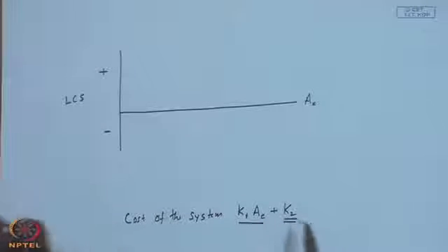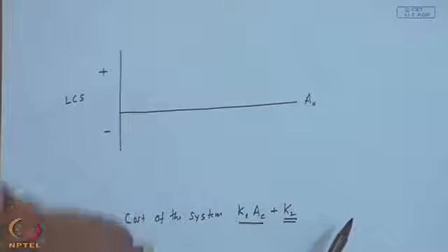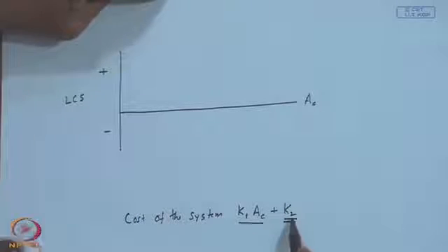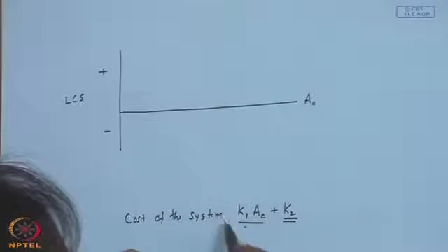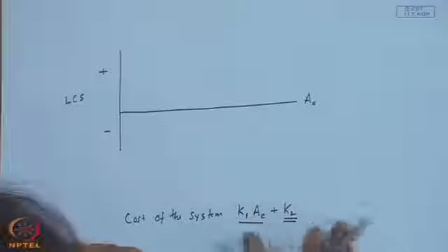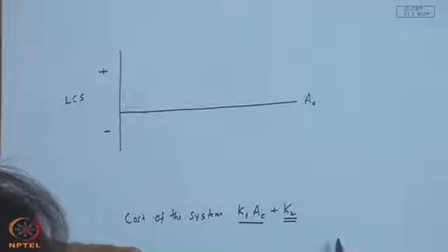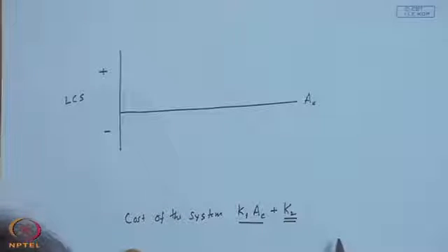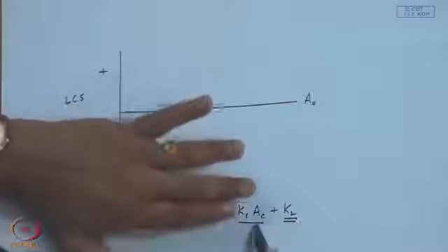The other one is a fixed cost, for example, that of a pump, right. Unless the area changes a lot, the pump cost is independent, similarly the heat exchanger. Consequently, you can by and large divide the cost into an area independent cost and an area dependent cost. Okay. What are the components that will go in is a matter of detail, but for the purpose of explaining this, you can say that the total cost of the system is something like mx plus c. So, this c is independent of the area that you have put in.